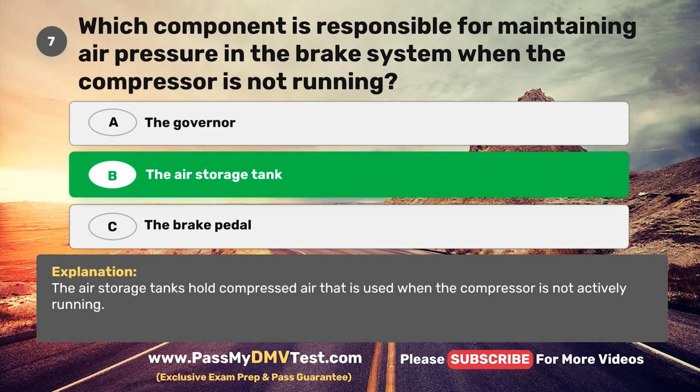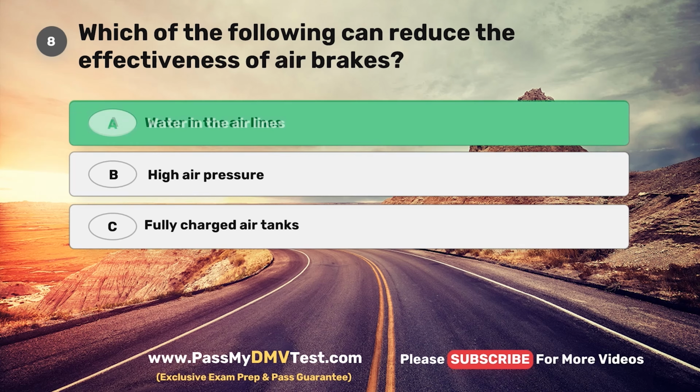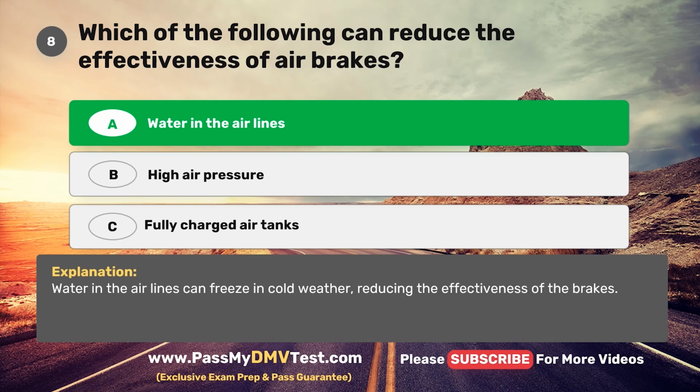Question 8. Which of the following can reduce the effectiveness of air brakes? A. Water in the air lines. B. High air pressure. C. Fully charged air tanks. The correct answer is A. Water in the air lines. Water in the air lines can freeze in cold weather, reducing the effectiveness of the brakes.